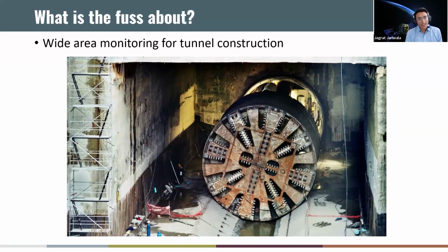There has also been a study wherein folks found the actual zone of influence was much larger than previously assumed. And now the benchmarks of the survey control points were even moving. Now, if that happens, the movement estimates from those systems are biased. And at that point in time, folks use InSAR to back calculate actual movement estimates.